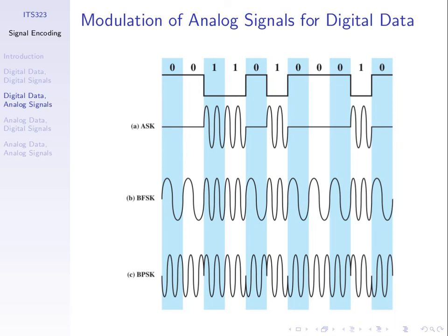This diagram shows some example of data we want to send. So at the top, the sequence of bits. Ignore the digital signal there. That's not useful for this example. Then it shows an output analog signal if we're varying just the amplitude. And the scheme in this example is with bit 0, transmit with amplitude A to be 0.